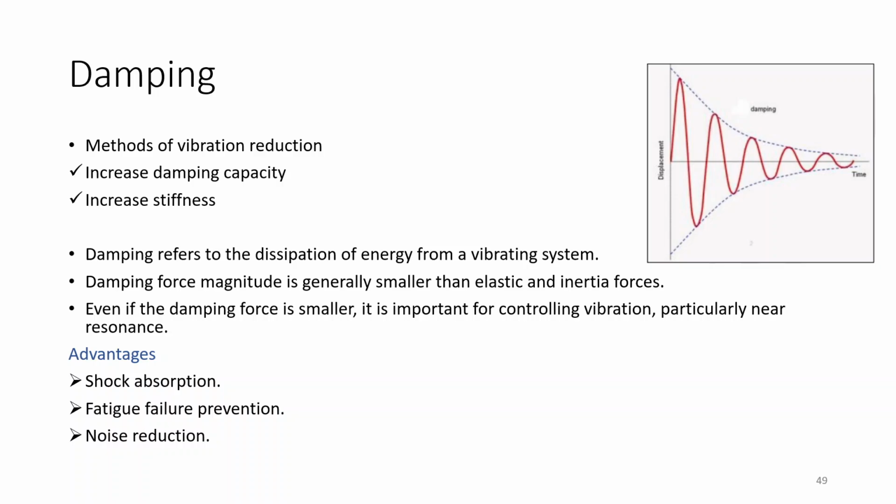To reduce vibrations, the methods are to increase the damping capacity or to increase the stiffness. Damping here refers to the dissipation of energy from a vibrating system.